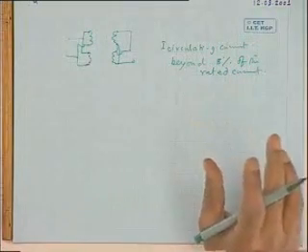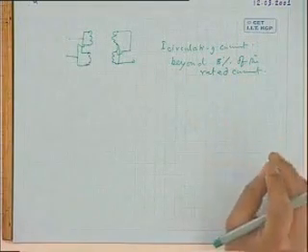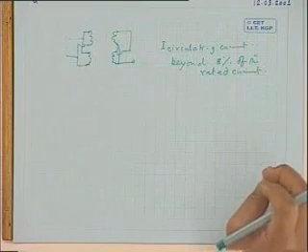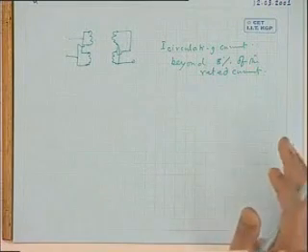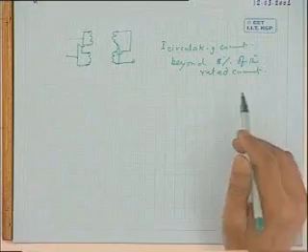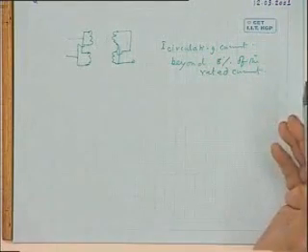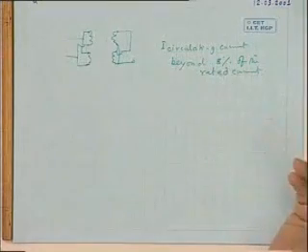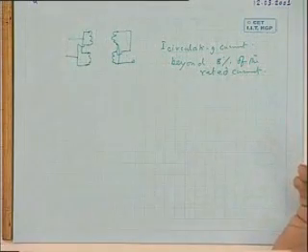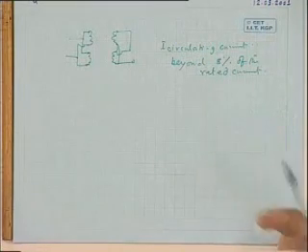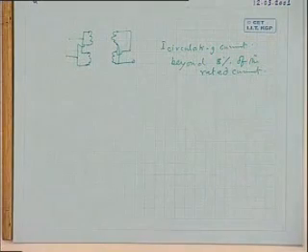The ideal thing would have been that the voltages are exactly equal, but in case there is a slight mismatch of voltage, it is not that you cannot parallel them. You can parallel them, but keep in mind that the circulating current does not exceed this 5 to 10% of the rated current, because this circulating current will simply add to the copper loss of the transformer and deliver no power to the external circuit.